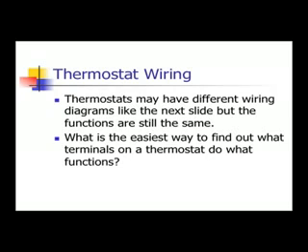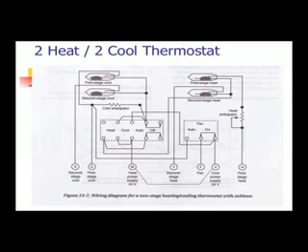You might have some additional terminals. C for common, it's the other side of the transformer. O might be a reversing valve for heat pumps. Y2 might be second stage cooling, and W2 might be second stage heating.